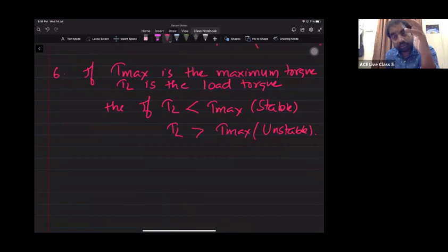R2, X2 naught, E2 naught are given, and when the motor is operating at a particular slip, you can calculate the rotor input, the rotor losses, the rotor output power, and the torque at that particular slip. Can you find out all these things? Yes, you can find out all these things.